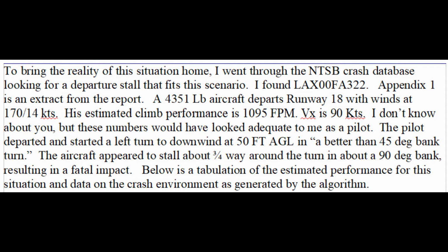The pilot departed and started a left turn to downwind at 50 feet AGL in a better than 45-degree bank turn. The aircraft appeared to stall about three-quarters of the way around the turn in about a 90-degree bank, resulting in a fatal impact. Below is a tabulation of the estimated performance for this situation and data on the crash environment as generated by the algorithm.